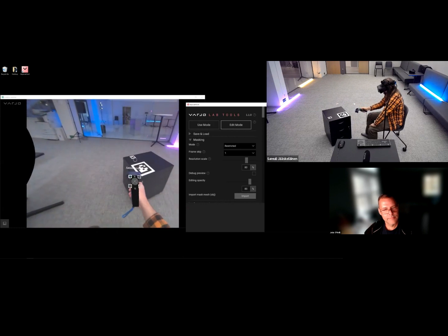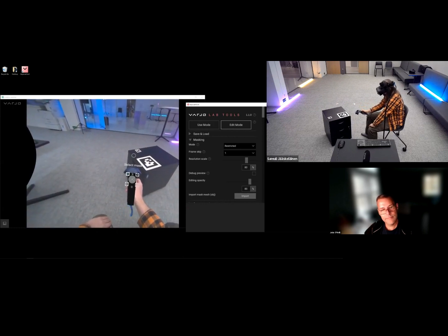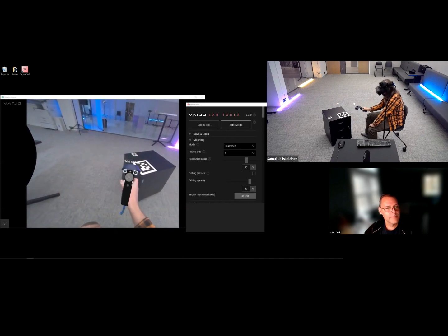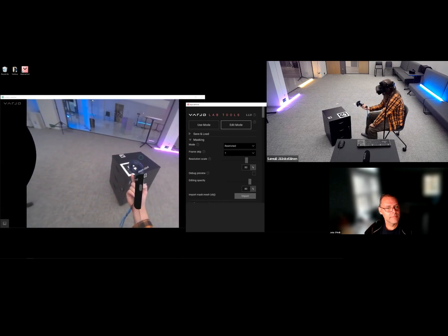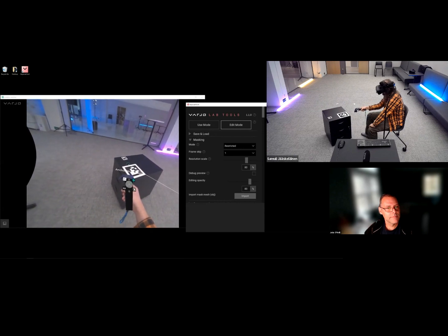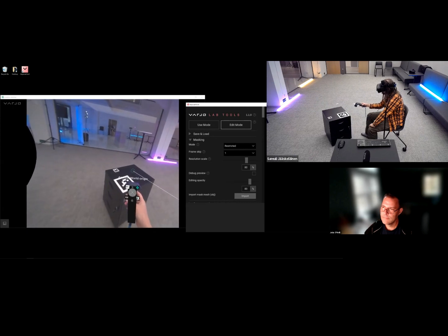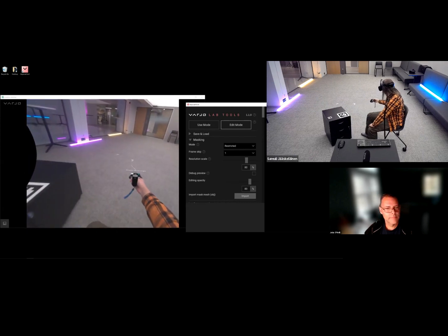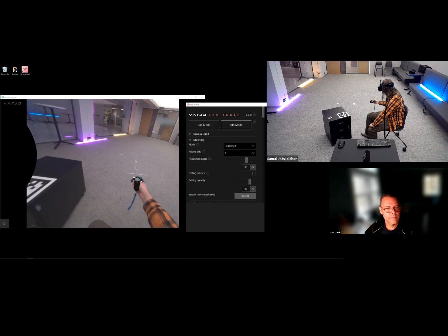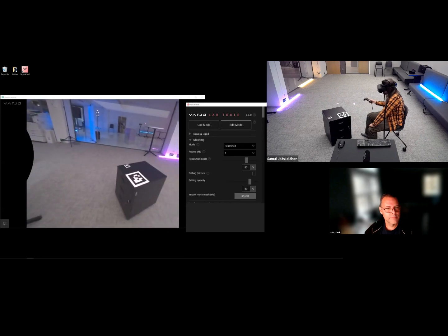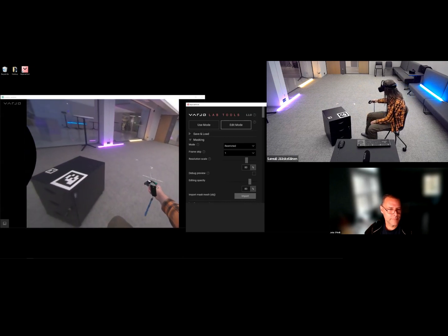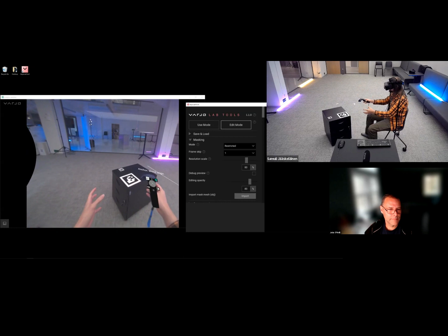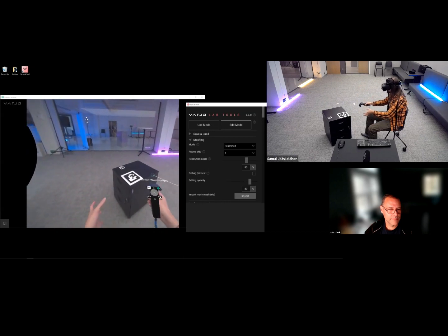So to make a new mask, I select the masking page and add a mask. Then just by clicking a trigger, I can accept that this is the tool I want to use. And then it will ask me a question, like, what is the anchor of this mask? Currently it's showing the middle of the room for an anchor, and that's because the Steam VR room setup here has that as an origin. So you can always anchor these masks into your world without any kind of tracker markers if you want.